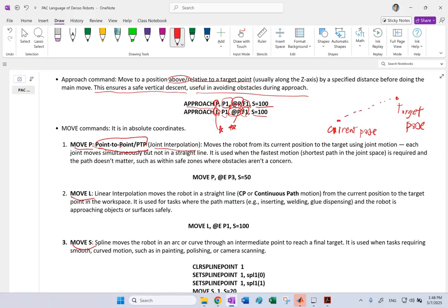To follow them, how would you do this path planning? Do you go straight with a line, because a line is typically the simplest thing to do? When you do this line, do you do it in the joint space or in the work space? If you do it between the Qs, on the joint values of the current pose and the joint values of the target pose, then that is called joint space interpolation, and move P.